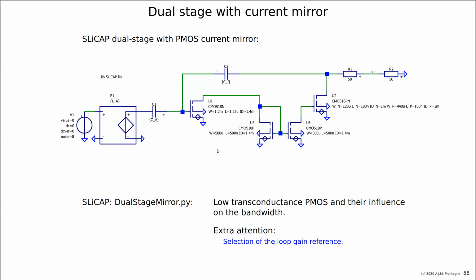Now you would say, maybe, are we just going to put the capacitor to 0 and then the whole circuit changes? Well, remember, in most cases, if we do a correct design, then the feedback capacitance says something about the sum of the poles, but not about the product, because it's much smaller than other capacitors. Look, for example, at the first transistor. Maybe you can imagine the small signal diagram under it.